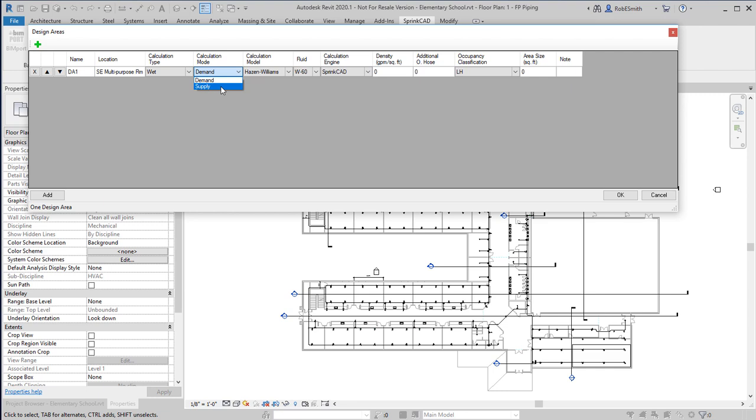If your goal is to perform normal NFPA 13 calculations, they are demand style calculations. The program is capable of calculating with both Hazen-Williams and Darcy-Weisbach formulas. Hazen-Williams, the more normal for the NFPA, defaults to water at 60 degrees.